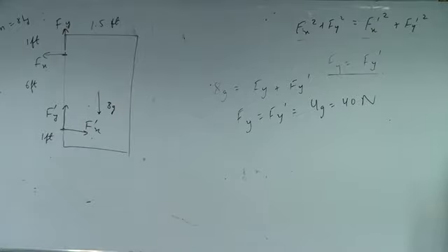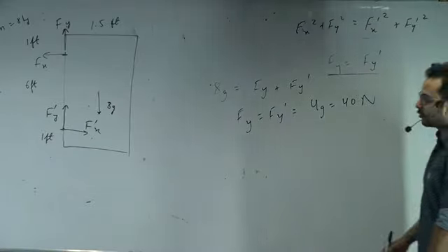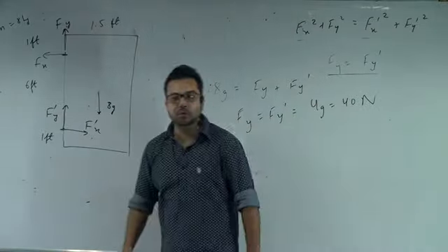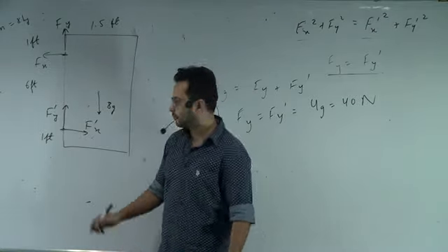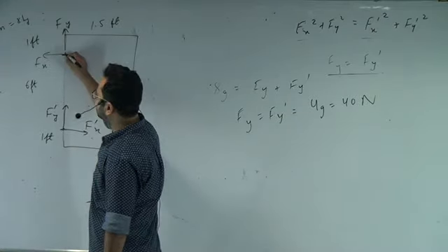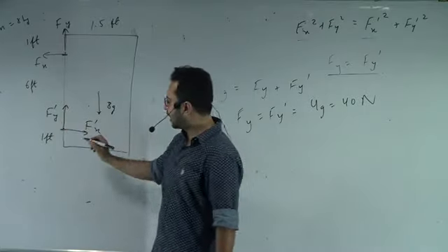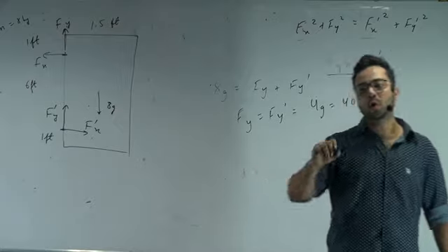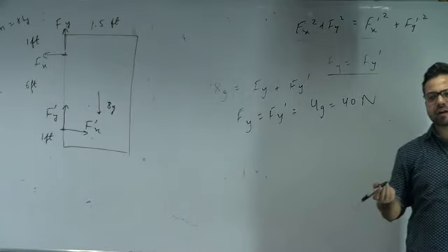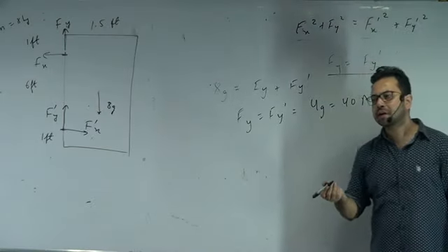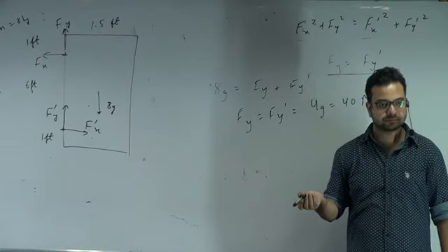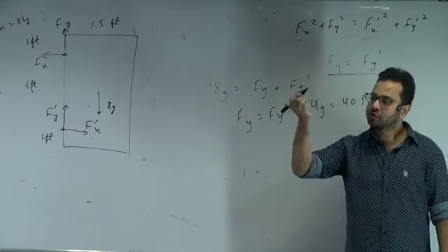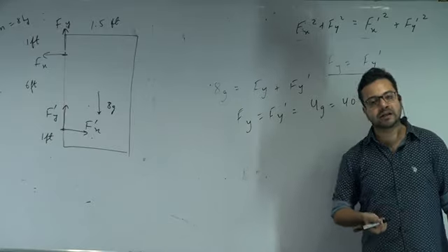Torque equation, yes. We have to use the torque equation. And about which point should I write the torque equation? Either this or this. Both will do. Alright, so I'm writing the torque equation about this hinge. In most of the cases when we are dealing with a hinge, it will be good if you write the torque equation about the hinge, because that way the forces of the hinge would not have any torque.